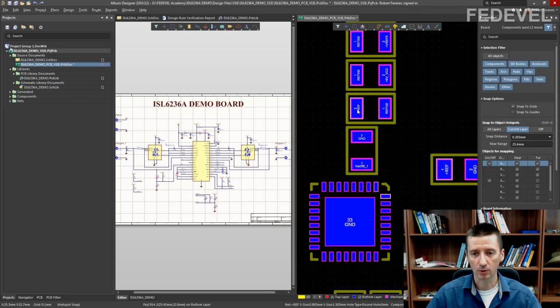It means these two tracks, they will be crossing somewhere here. And there is easier way how we could do the layout. What can we do? If we simply rotate this resistor, then we can directly connect these pins here and this one here. So let's try it, okay?